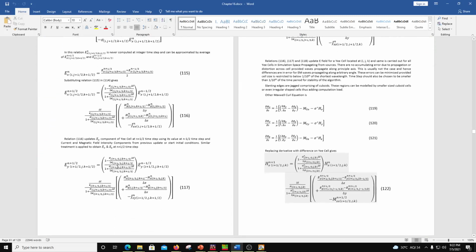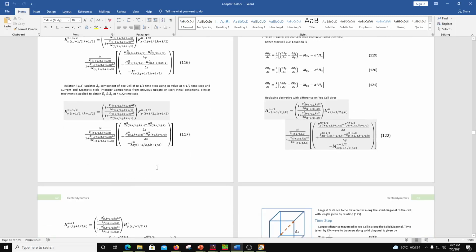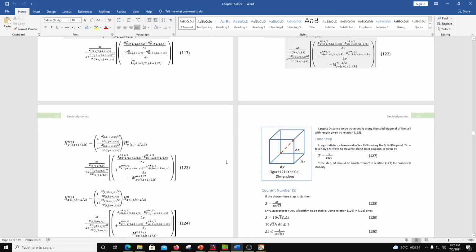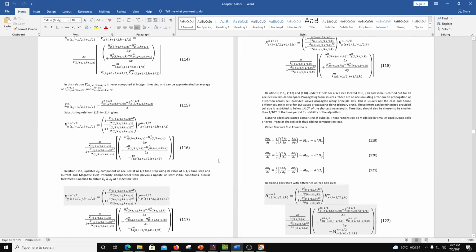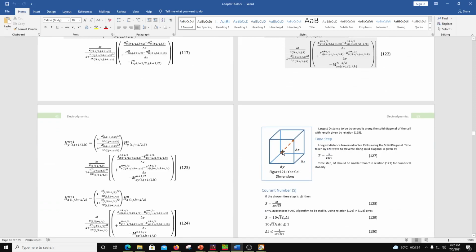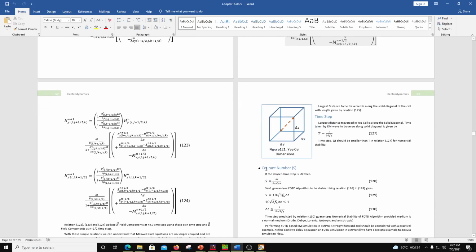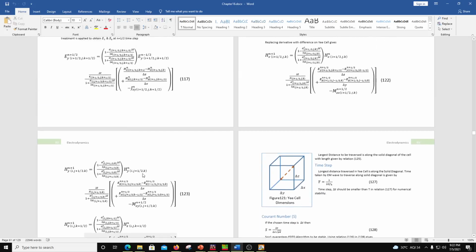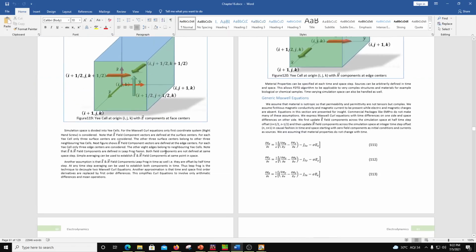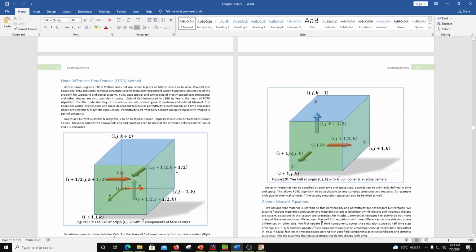This is what is written inside your XFDTD, or your EM Pro FDTD, or any FDTD in the world. The Courant factor I was talking about is this diagonal element. This is going to give you dispersion, so this is called the Courant factor S. Your sizing of a grid should be such that this is within tolerance, so that the computation will be stable, and then there are perfectly matched layers and stuff like that.